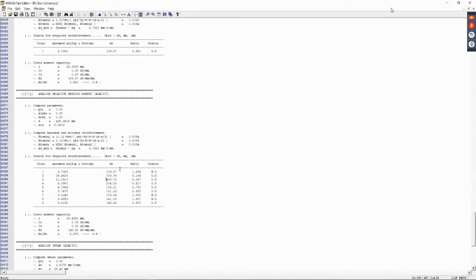So basically you can choose to use the assumed area of steel for the top and bottom for your reinforcements based on the ratio or the design that is done by Midas. Just take note of it, and then you can run it for checking afterwards.